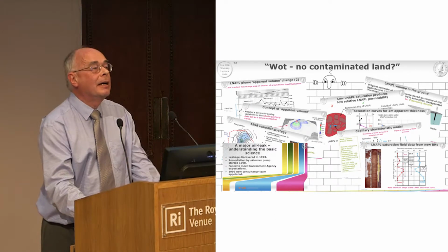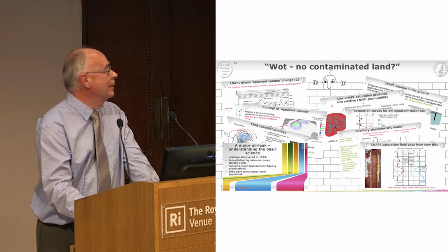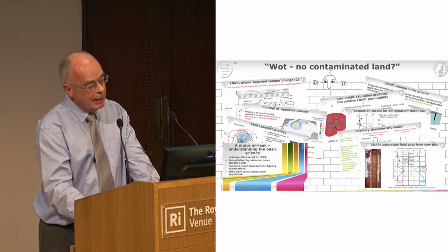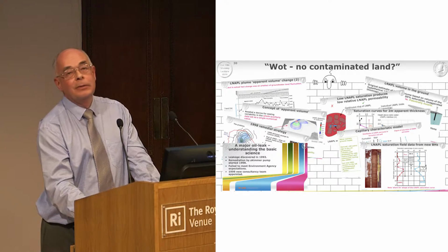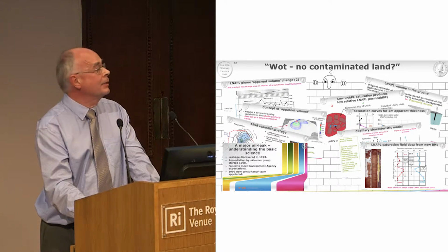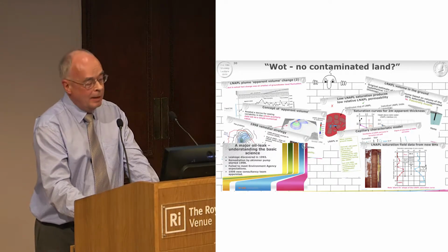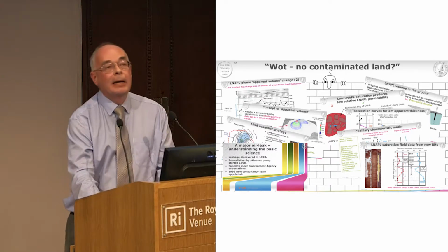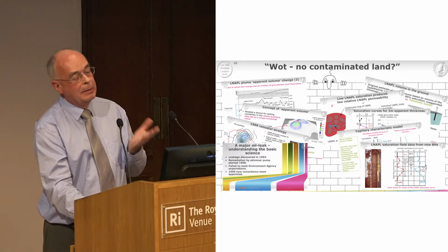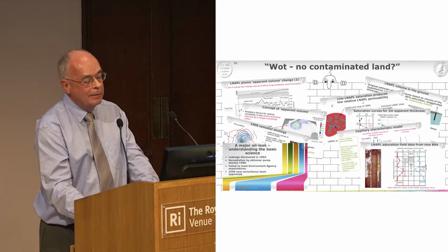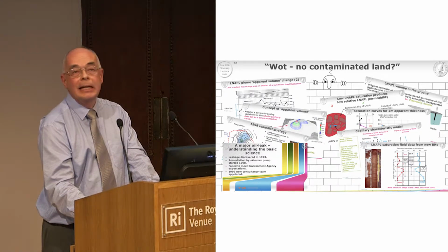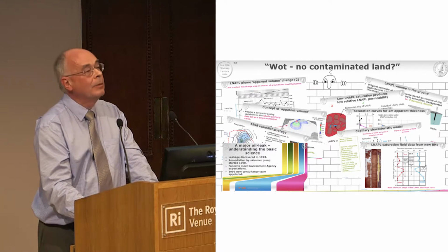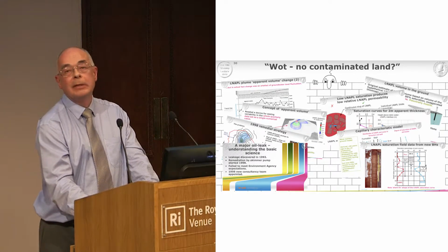It concerned an oil leak of something like 9.5 million litres into a principal aquifer. And the original consultants on the site basically hadn't understood what was going on because they had a too simplistic ground model. And SRK came along and we re-looked at it, and through a number of lines of evidence managed to understand the basic science. The physics was actually going on in the aquifer, and therefore we were able to propose workable remedial measures.